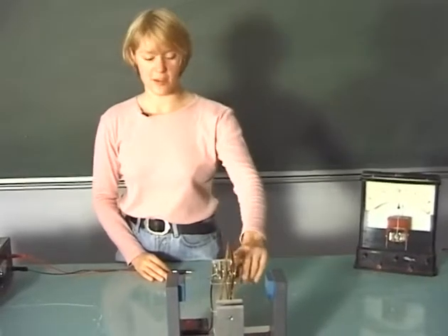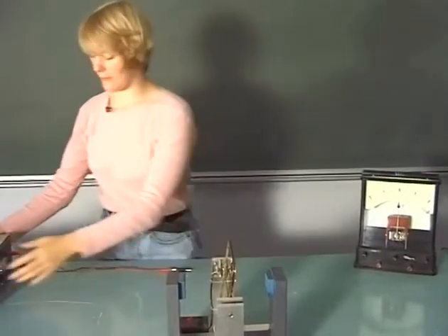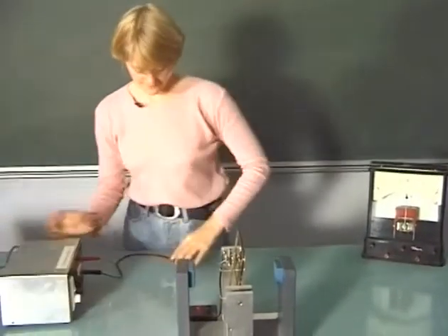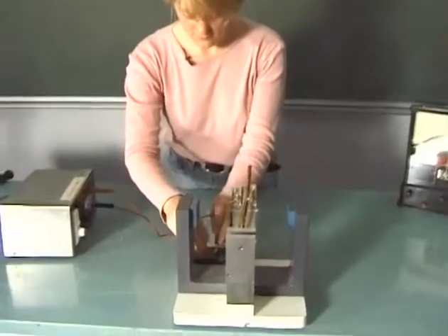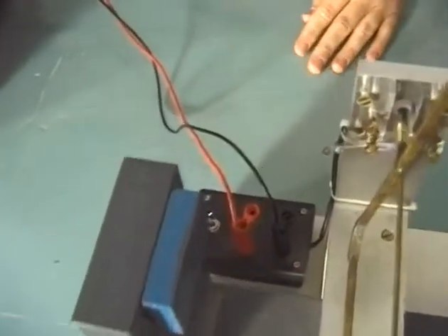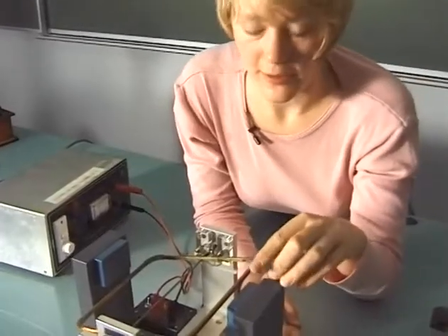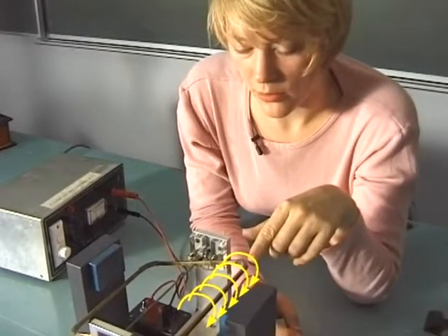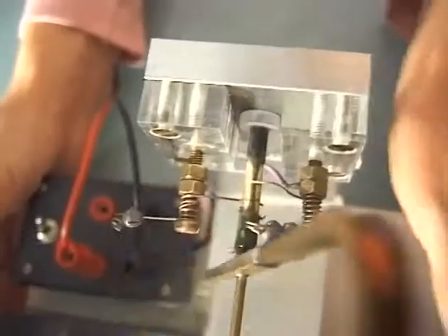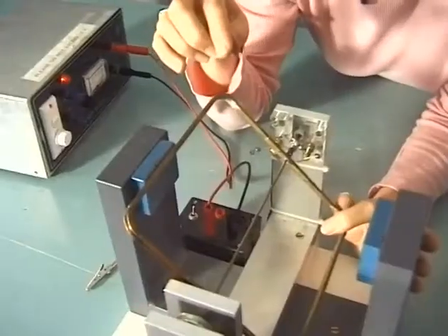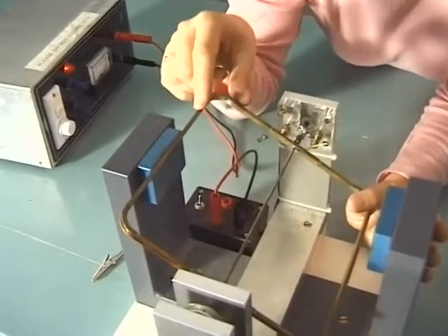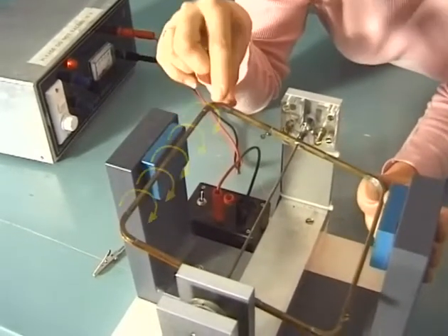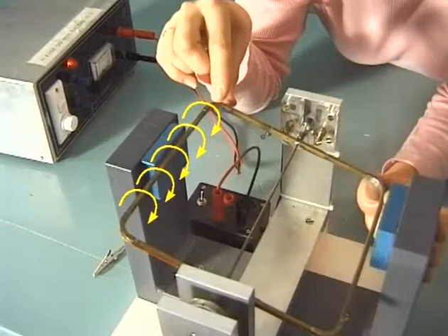This generating device can also act as a motor if we connect a power source to it. Now we can change the generator into a motor by putting current through the wire, which creates a magnetic field around the wire. That magnetic field, when it passes the poles of this magnet, will oppose it and force it to travel in the one direction. When it gets around to here, the current's been reversed. We're on a different pole of the magnet, so the force is going to be the same direction.